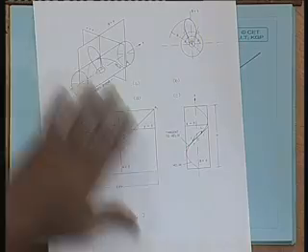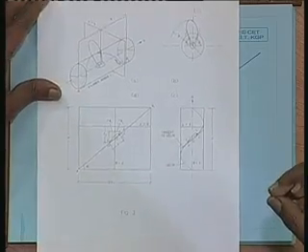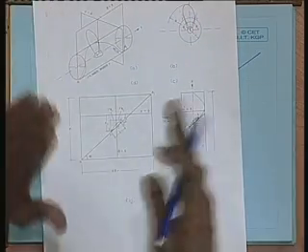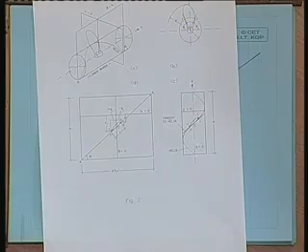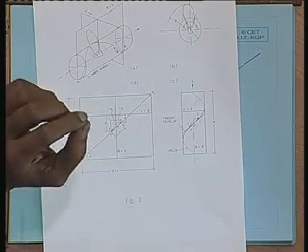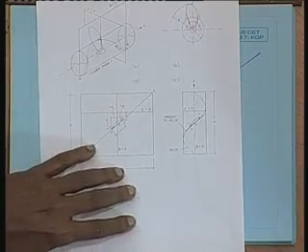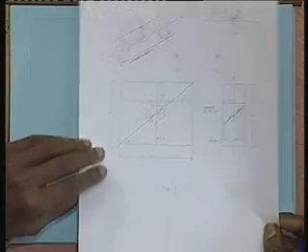Right now, let us just understand that though we are defining the propeller blade as a helicoidal surface and defining P as the distance moved in one revolution, in the actual case the propeller may not move distance P in one revolution because the medium is not solid. There will be many other reasons, but one of the main reasons is that it is not solid. To overcome the resistance in a solid medium, we are actually applying manual force to move it. In a fluid medium, what happens, we will see as we go along the course. Have I been clear?